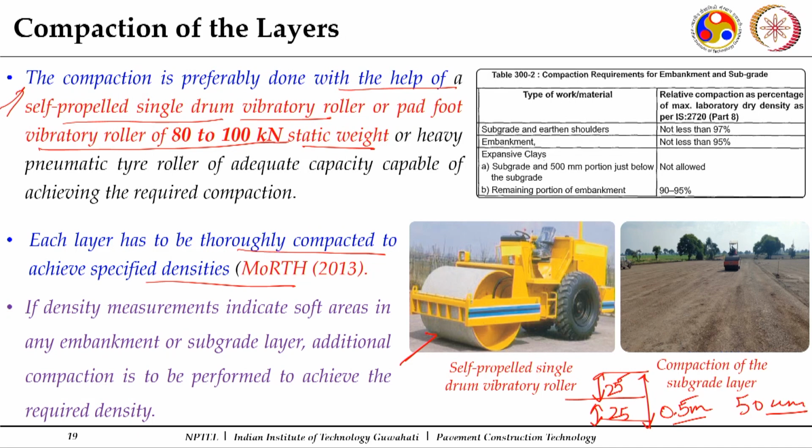So, for subgrade construction, if I don't have these vibratory rollers and I am going with the static rollers, then I may have to compact layer thicknesses of 20 centimeter, and the top one will be 10 centimeter. Instead of doing it in this manner, the other way around I can do it: the bottom one of 20 followed by the top 30. If I am going with the static rollers, I will prefer 15 centimeter and 15 centimeter. So, each layer thickness needs to be ensured.